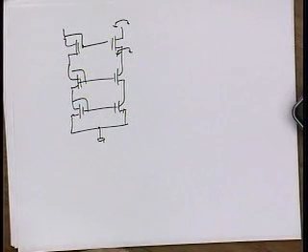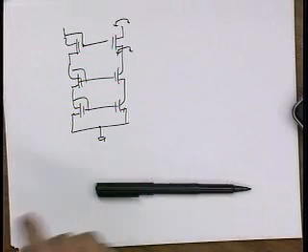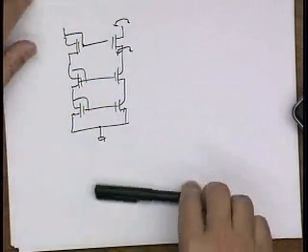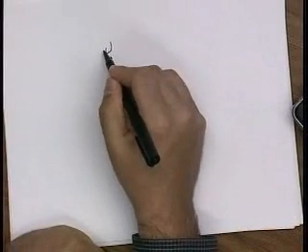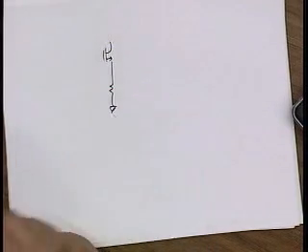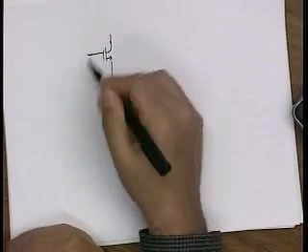And so the other technique that's becoming popular now is gain boosting. Okay? So the idea of gain boosting is that we're going to use feedback in order to boost the impedance. And the way that I like to see how gain boosting works is to go back and look to see how a cascode actually attains high impedance. And so in fact, a cascode already is using feedback, right?